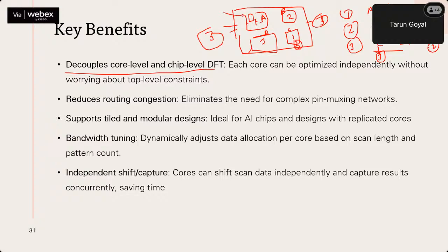Now you were treating it as a small core, but the actual requirement of A is, suppose, three channels. Now you again go and change your planning. My core A requires three channels, and then there is core B. My combinations will be: in the first combination, I'm running core A. Second, I'm running core B, or maybe I do core C also to optimize my test cost.